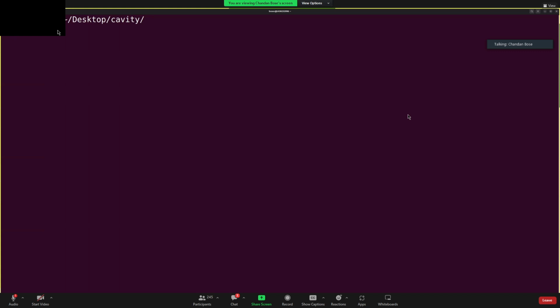Can you write in the chat box? Which command do we use to go back to the installation folder? Foam, provided the fact that my OpenFOAM is activated by sourcing the bashrc, which is done already. So the right answer is foam, and we go to the installation folder, OpenFOAM 2306, and then we go to applications and solvers.